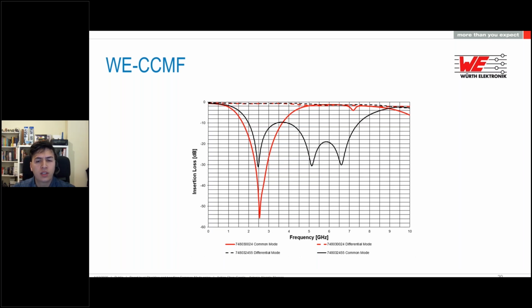Compared to the traditional common mode chokes, which are ferrite based, which have a wide broadband with attenuation at different frequencies, in this case, for these new interfaces with higher speed, higher switching, we designed it to resonate at this frequency.